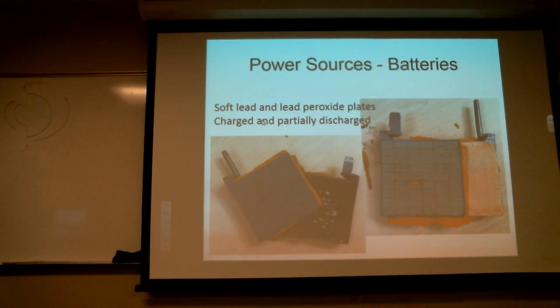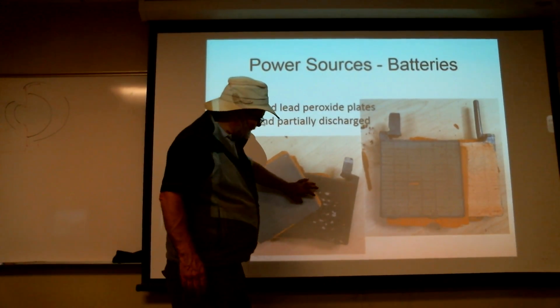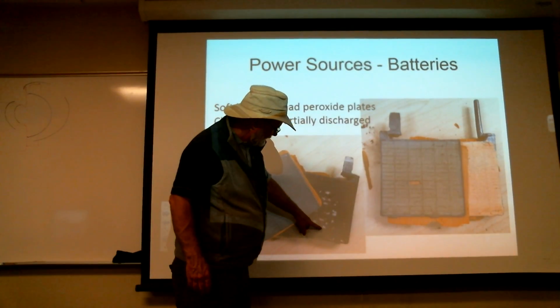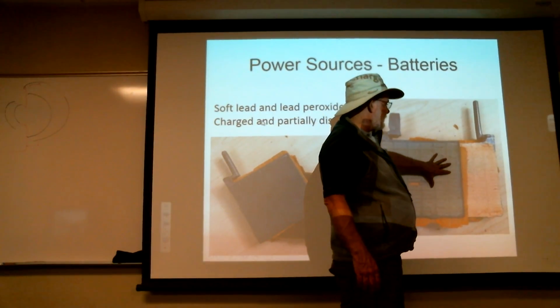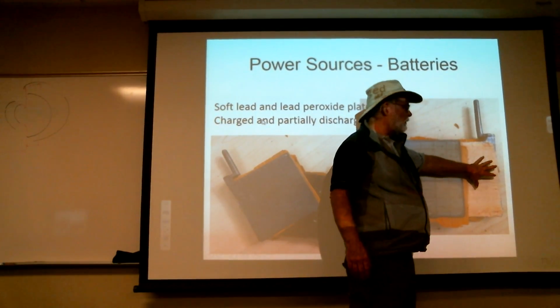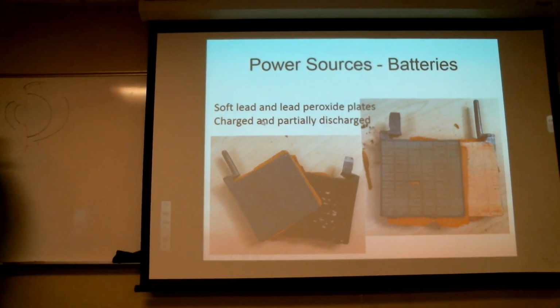Okay. So yeah, in fact, I took pictures of this apart. So you can see the lead peroxide, and you can even see just sitting on the shelf some damage occurred. Here is your lead sulfate from the porous lead and lead sulfate formed from the lead peroxide. They look a little different because of the direction they're coming from. But if I continue to do that, both of them would look closer and closer alike. They're not trying to meld into each other, but they're both heading towards pure lead sulfate.